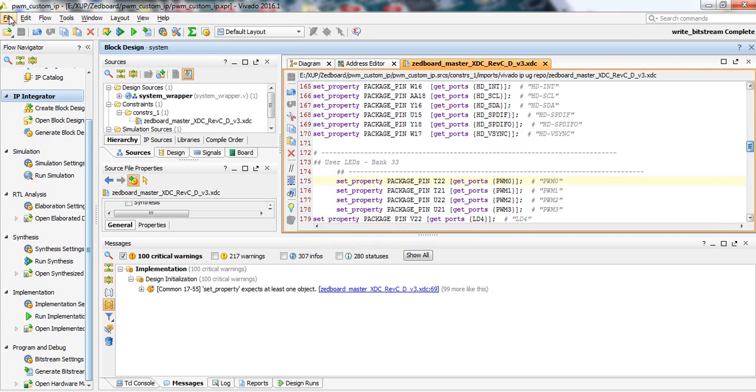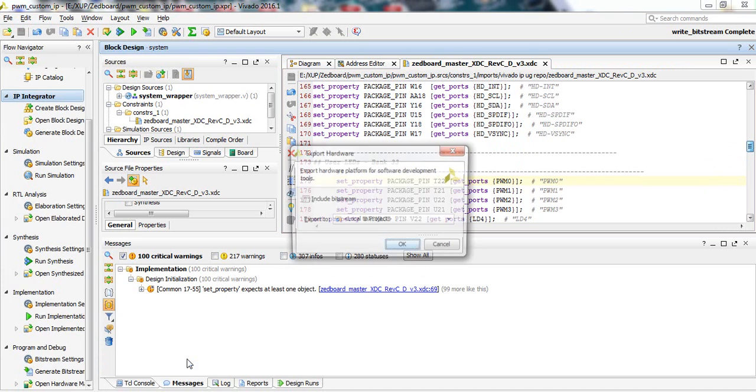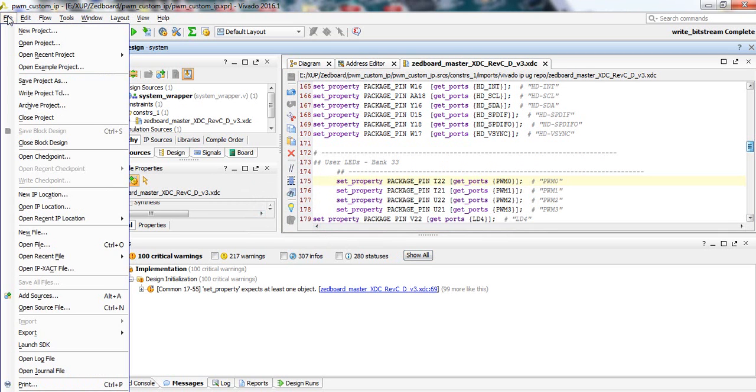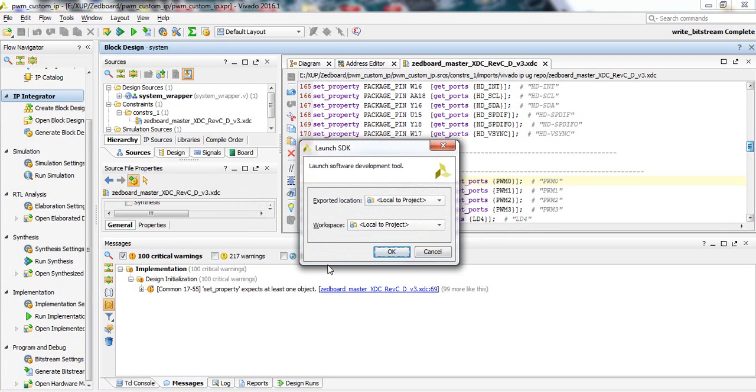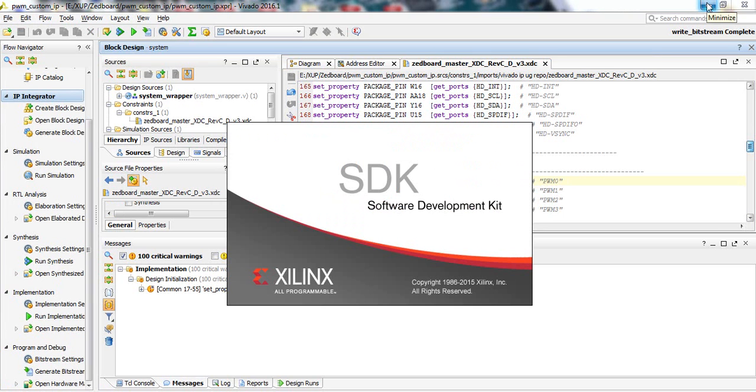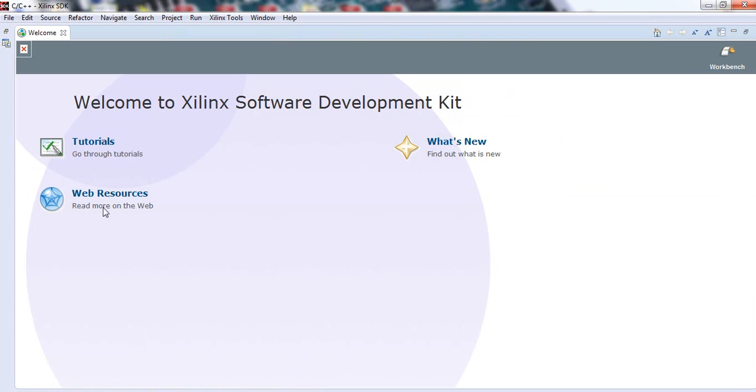So we are going to do Export Hardware and include the bitstream. We're going to click OK. It has been done. Then we will launch the SDK from the local project directory. So let's wait some time for launching the SDK. Okay, it will execute soon on my computer. We are already at the 23rd minute of this video. We need some time for launching this SDK.